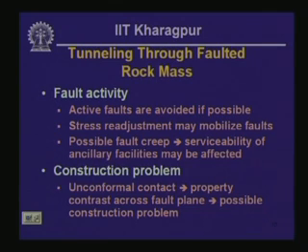Construction problems might also arise in the construction of tunnels through faulted areas. Faults are unconformal contacts in which the rock mass on either side of the fault plane could be of remarkably different stiffness and strength characteristics.